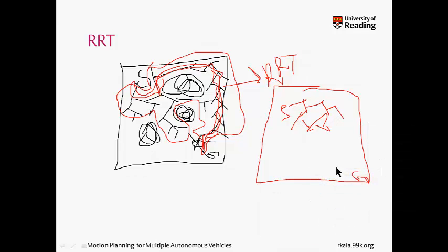The way that I extend this graph is very simple. Step 1, I generate a random point anywhere inside this map. I find out the closest point in the RRT available, and I simply extend this point towards this X by a step size, say S. And if this complete edge is obstacle free, then I add it to the RRT. Similarly, next time step, let's say this is the random point generated.